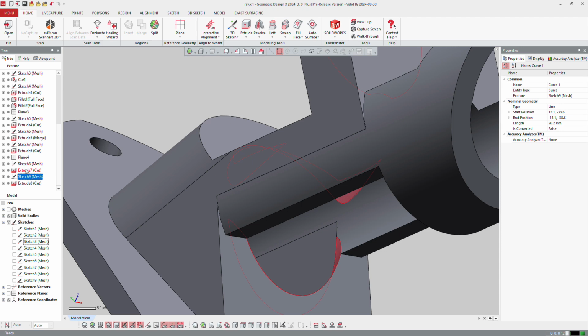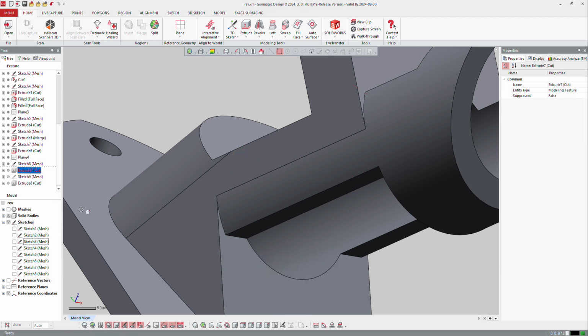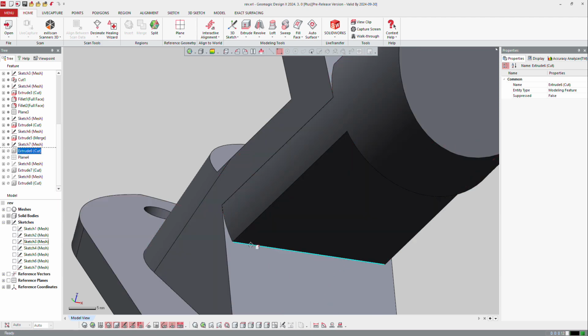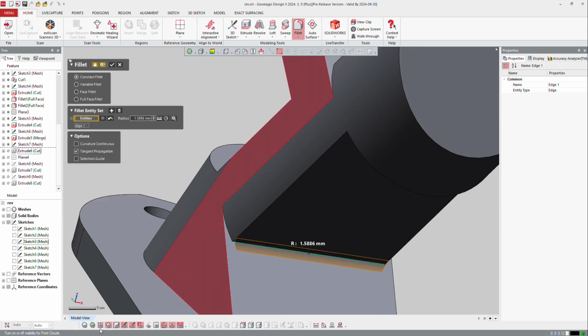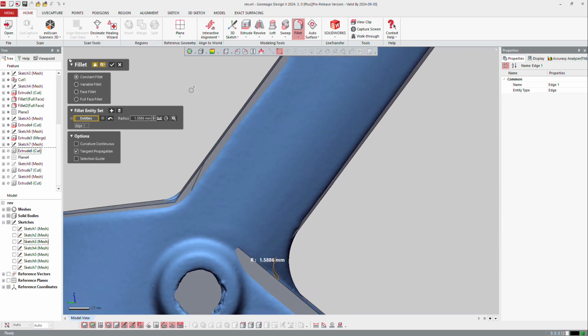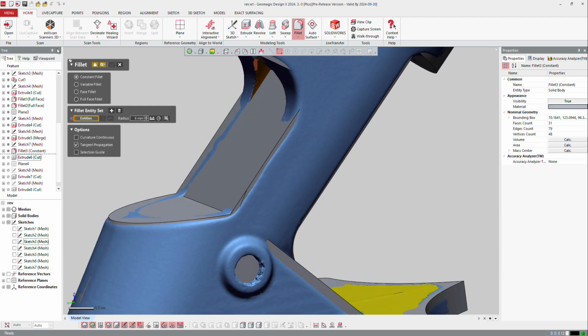So where was my cut here? Roll back. And again, a little bit before the first cut. So roll back again and right mouse click there, and I would make a fillet. I can always display the mesh, and you can see the shape. Here I can ask to estimate, but here it should be maybe 5 or 6. Yeah, 6 looks better.